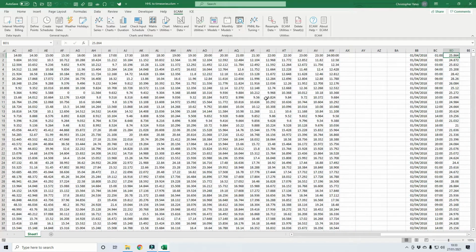Now what that's done is rendered it down to hourlies. So these are half-hourly figures, and these are rendered down to hourlies here. As you know, a very common format, and I'm working with the most common format, is kilowatt hours, and these are kilowatt hours in a half-hour period. So getting them into hourly figures makes them kilowatt hours in an hourly period, which, as you know, is average load in kilowatts over the hour. So there we go. That was the electrical, wasn't it?